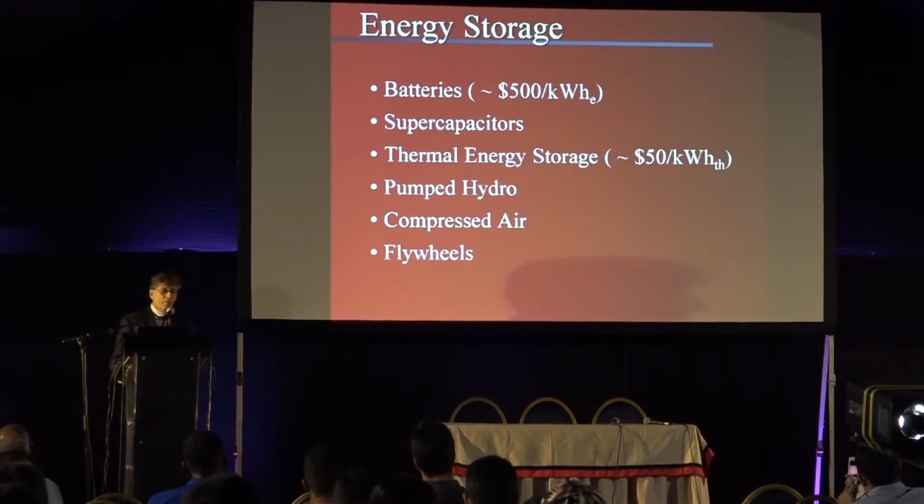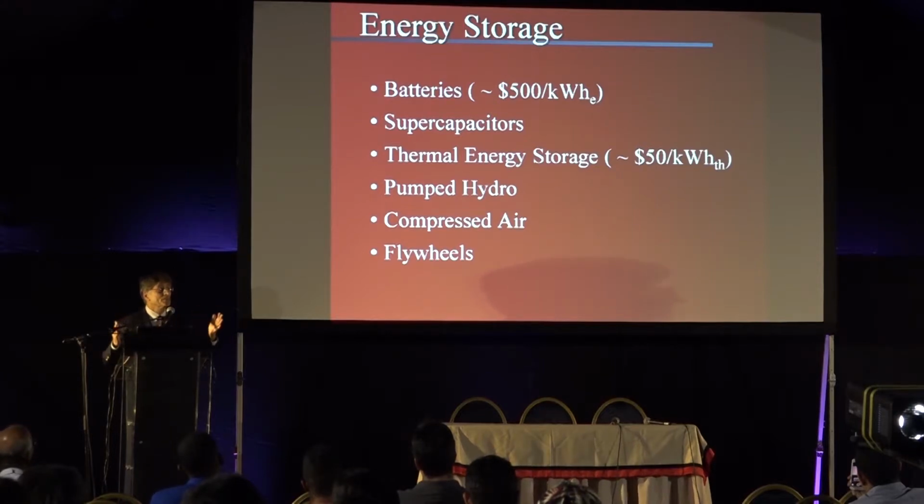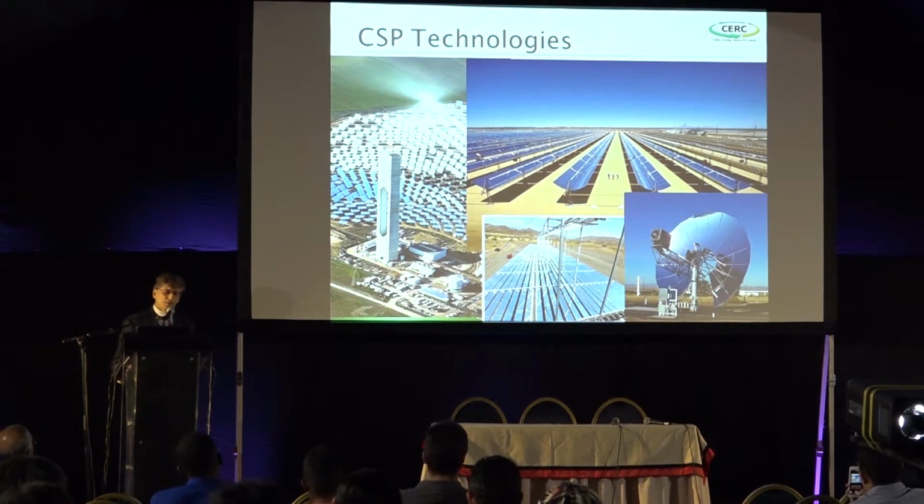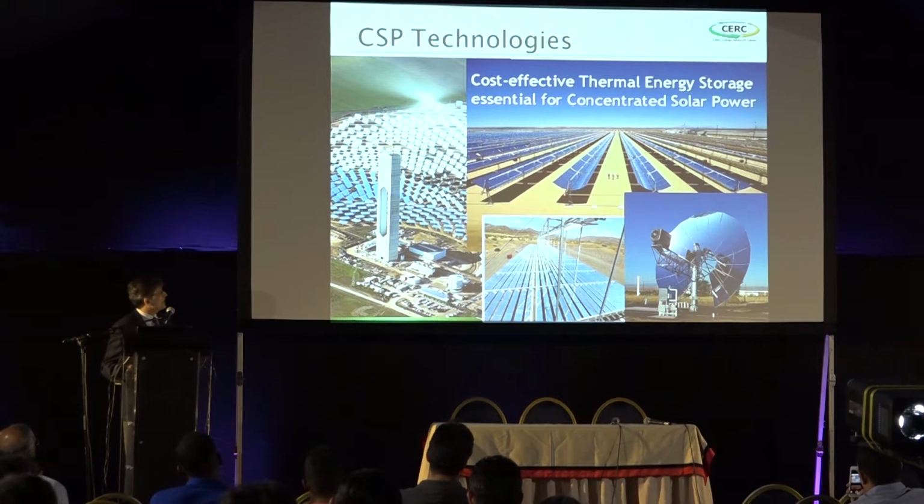So battery storage has the advantage that even when you need a small amount of storage, you can put in batteries. Thermal storage would be more applicable to larger scale solar power plants. But the cost being so much lower makes a lot of sense when utilities are looking into solar power plants, that they look into thermal energy storage. So, as I said, cost-effective thermal energy storage is essential.